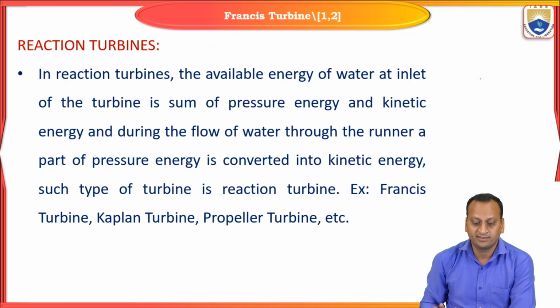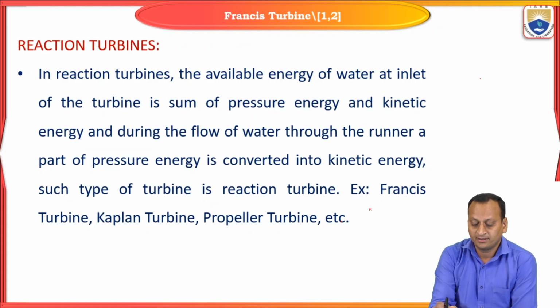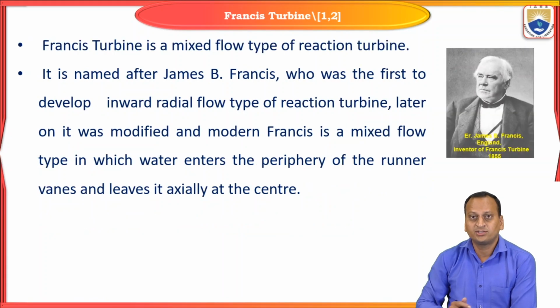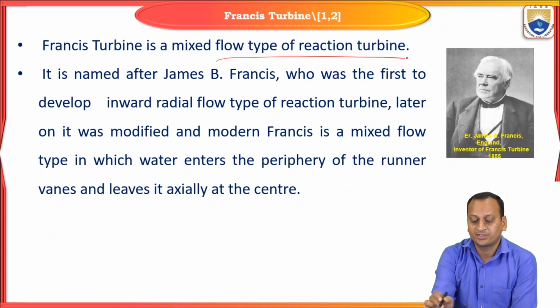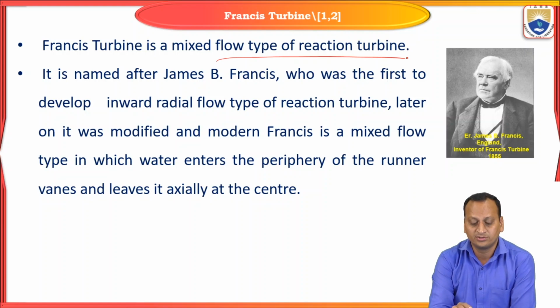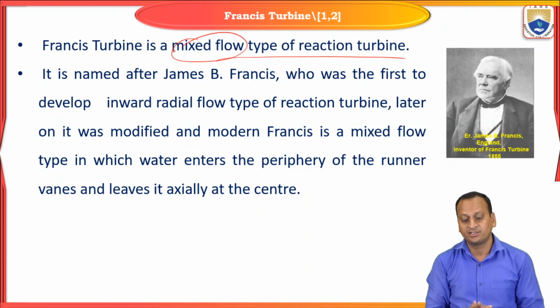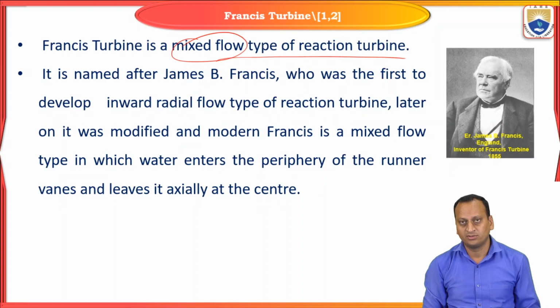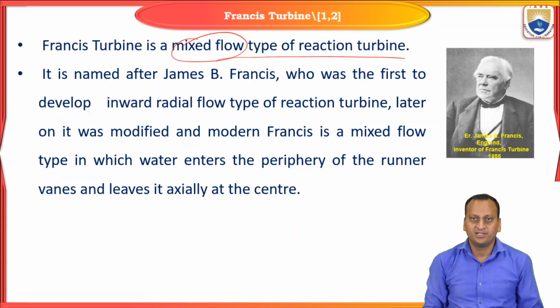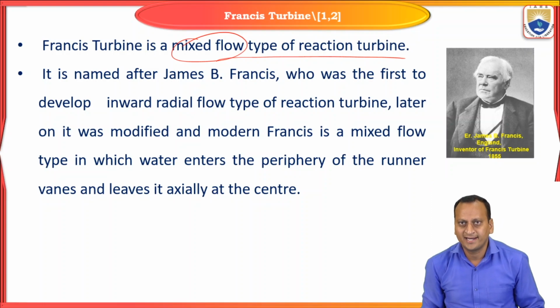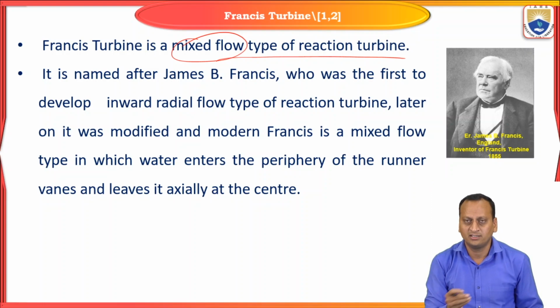So in reaction turbine, there will be Francis turbine, Kaplan turbine, propeller turbine, etc. The Francis turbine is a mixed type of reaction turbine. So as we have discussed now, it is a reaction turbine, but mixed flow. There will be axial and radial flow. The entry will be radial onto the blades of your turbine, and while leaving, the flow direction will be axial, meaning it is parallel to the direction of rotation of a shaft.